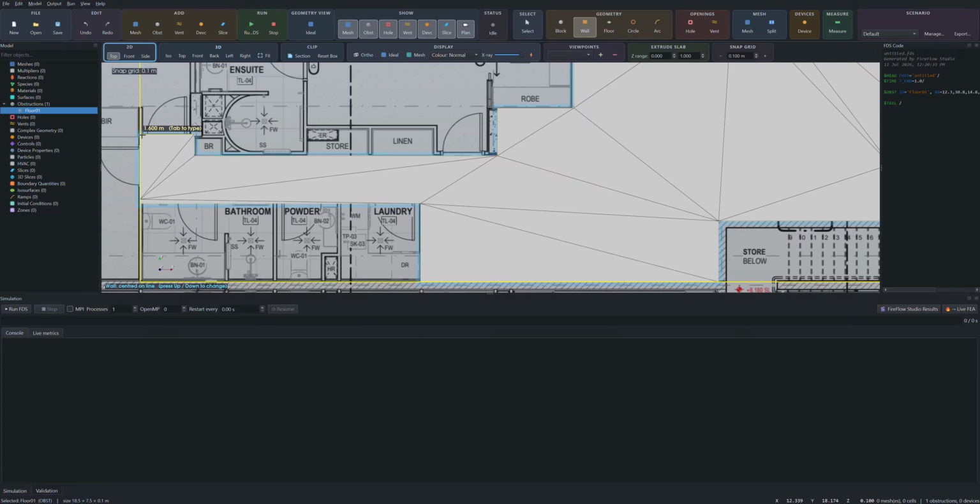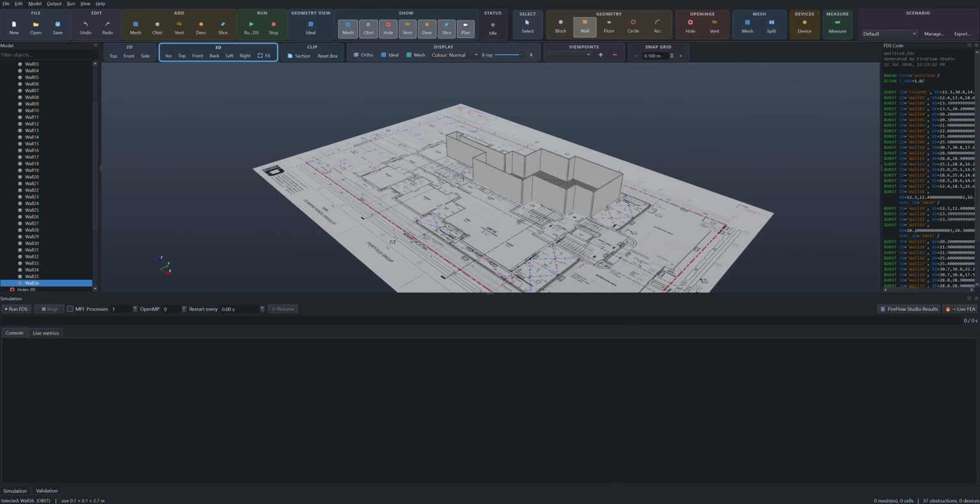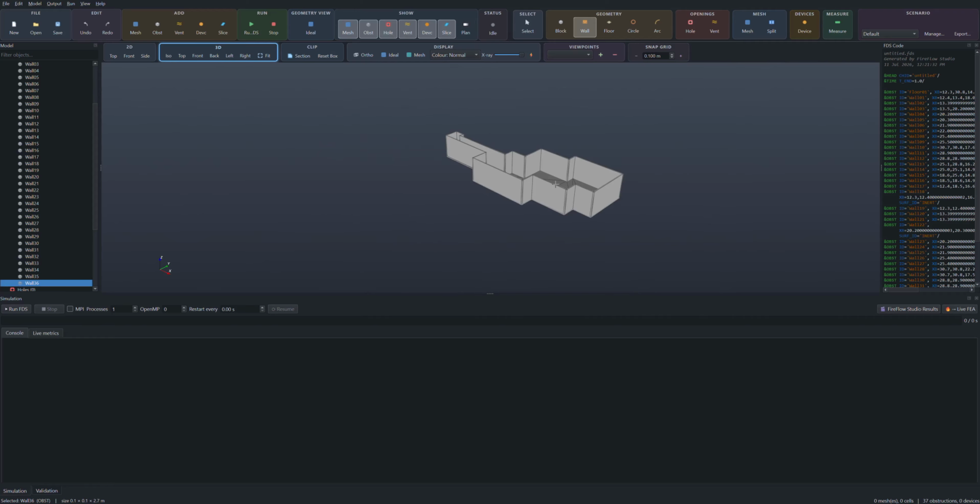Now what you will notice is if I press up, it'll align it internally. If I press down, it's centrally aligned, and if I press down again, it's externally aligned. So let's align it internally and complete the line. Let's put a height of 2.7 meters, thickness of 0.1 and create. Now I've got a 3D model just like that. So let's switch off the plan.